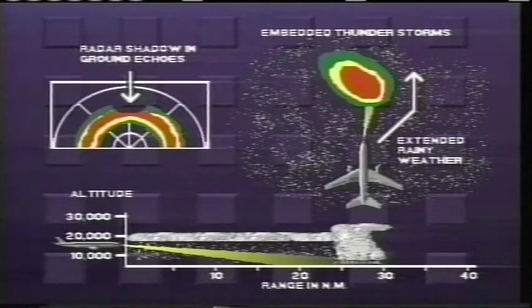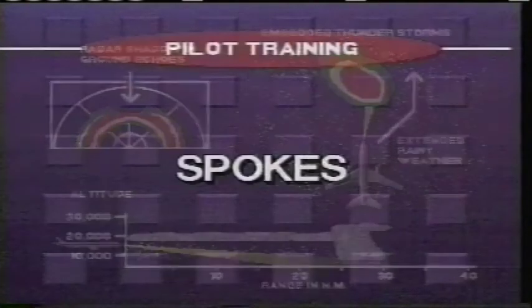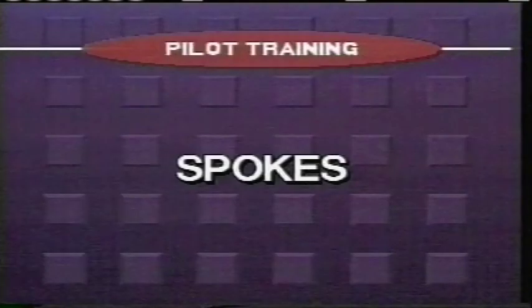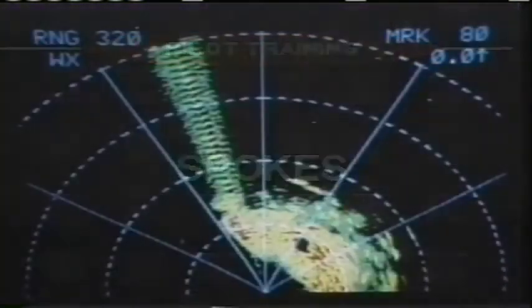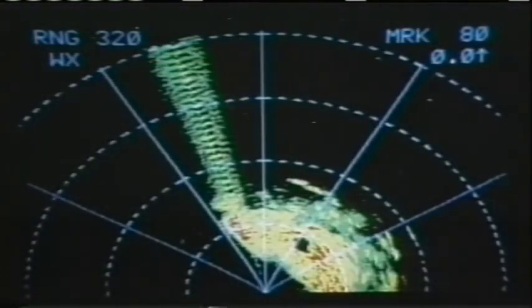Although the procedure described works well in extended rainy conditions, we cannot overemphasize that weather radar should be used for weather avoidance, not penetration. The weather radar industry uses the term spokes to represent any presentation on the radar display unit which resembles wagon wheel spokes.